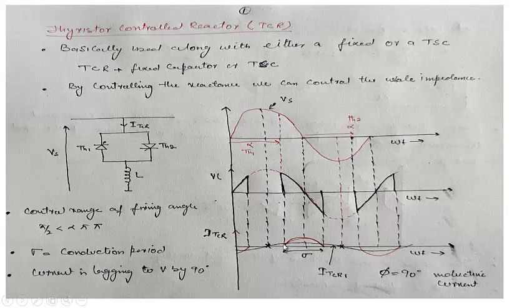Now current will start flowing in the circuit. Current will start flowing in such a way that the average voltage across this inductor will be 0. That means the current will be 0 at the point when the voltage from here to here will be the same as the voltage from here to here.